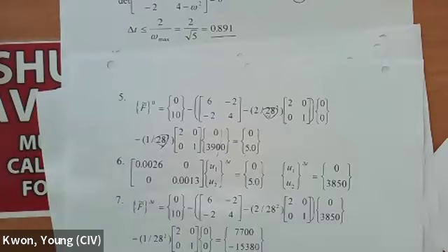In other words, if this is a vibration problem, then you have to go up and down like that. But as you continue, it never comes down, it just continues to increase the displacement, which means the solution blows up. Right? So depending on how close your delta t is to the critical value, the speed of that blow up is going to be fast or slow. If your delta t is much larger than the critical value, like what you see in here, then it's going to blow up very quickly after a small number of calculations. You got it?